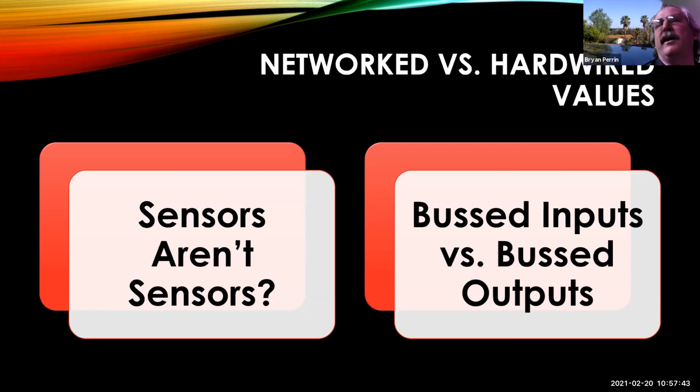Yes, but on the other hand, sometimes you will see really inferred PIDs. There is no sensor, but based on duty cycle, this is what a feedback would look like. Which is just kind of useless. So now you're chasing a sensor, and, hey, wait a minute, there isn't one.